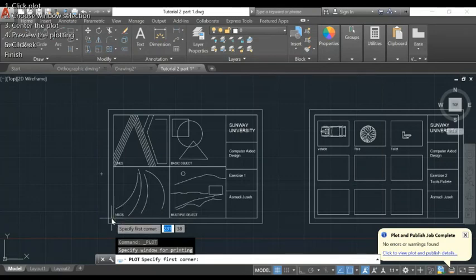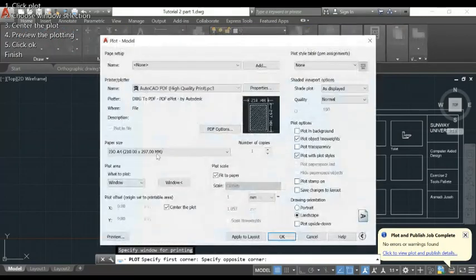When we are here, please remember you need to choose the borderline, not the paper. This is the borderline, as you can see here, and this is the A4 paper that we drew. So any time you are printing a technical drawing, please select from the left bottom of the borderline to the right of the borderline. Reminder again, not the paper, but select the borderline.